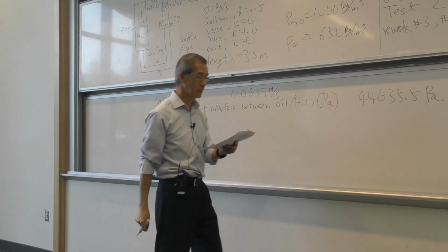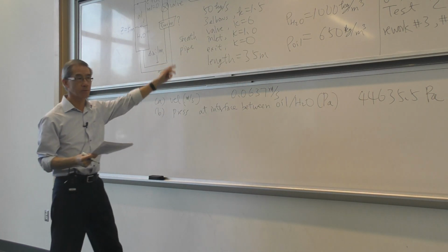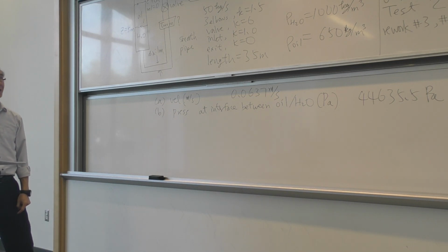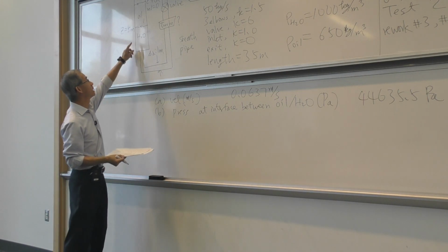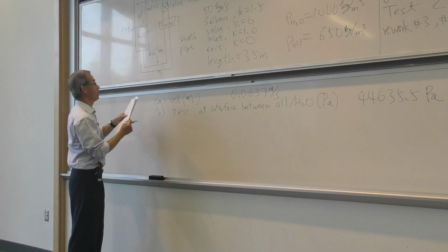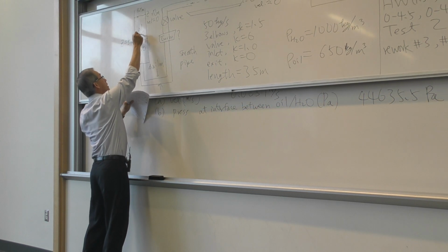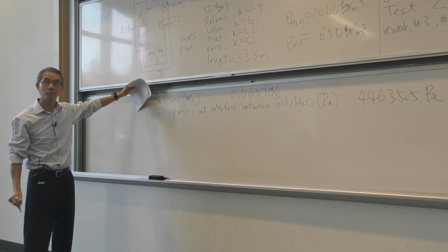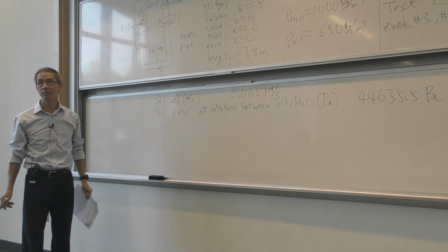OGH will give you that column of oil on top of the water is equivalent to about 44.6 kilopascal. And I'm jumping ahead, I'm having that part B set up so that I hope with that hint, you will use the energy equation at point 1, but not at the surface of the oil, because if you use the surface of the oil, you have a different density fluid.